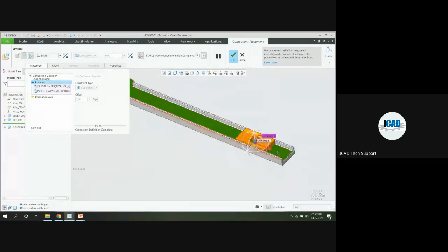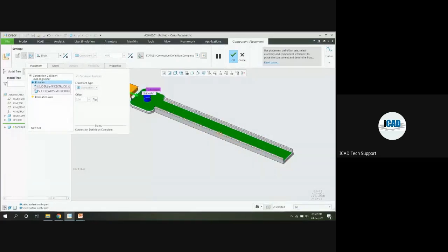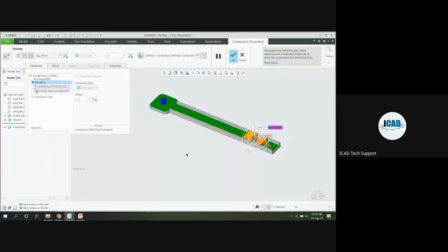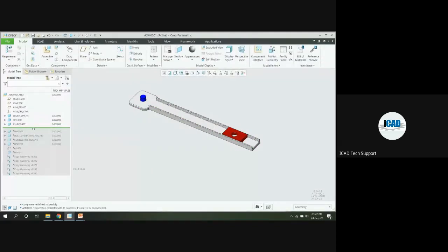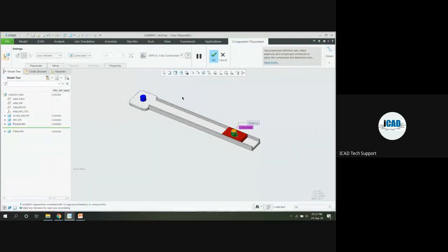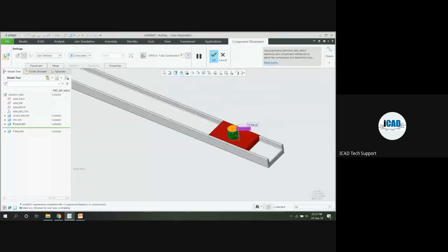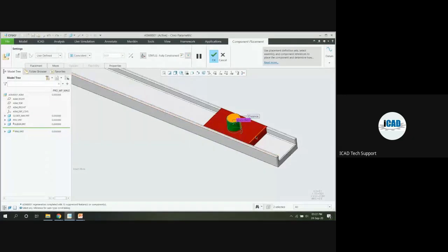Now again you can see the limits are not provided for what area I need to slide this slider. So first of all, I am leaving this slider as it is, and whatever links are available in between those, I will create. Here again the pin mechanism, as I said, the fixed pin mechanism we have created here, because with the slider the pin should travel.